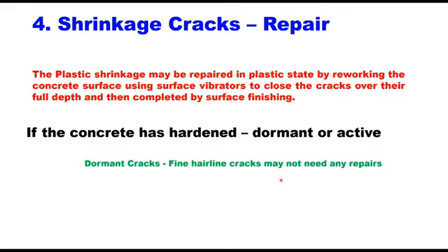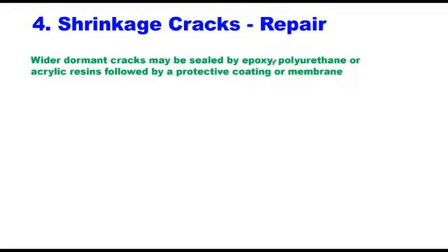Fine hairline cracks may not need any repair, but many times these cracks become a durability problem in future, and therefore it is always good to seal them by using some protective coating. Wider dormant cracks may be sealed by epoxy or polyurethane or acrylic resins followed by a protective coating or membrane.